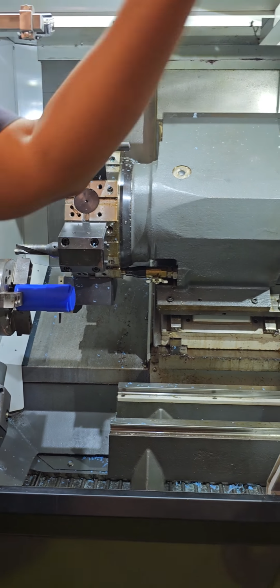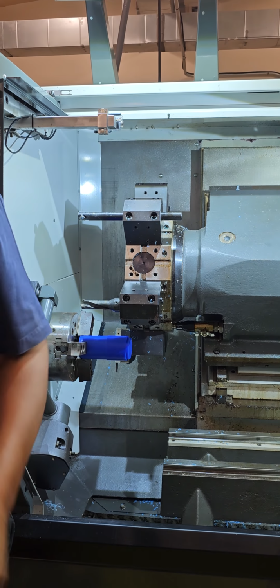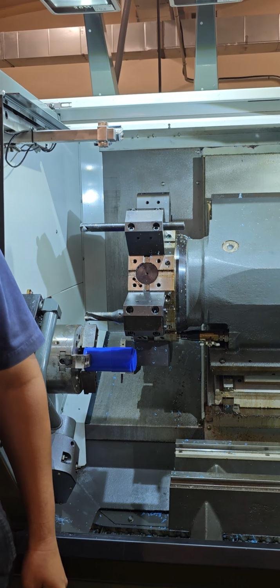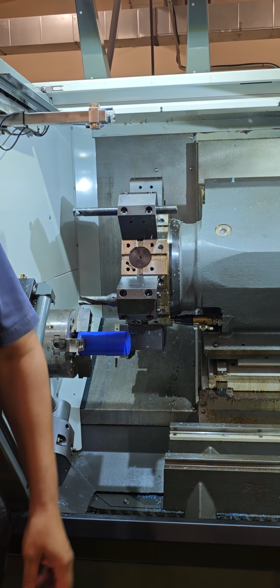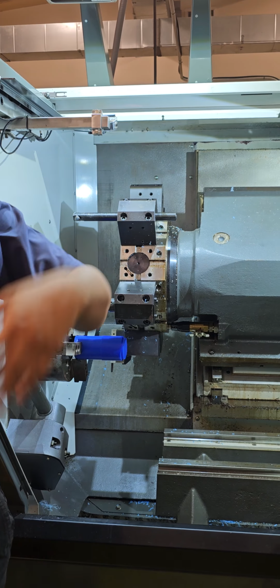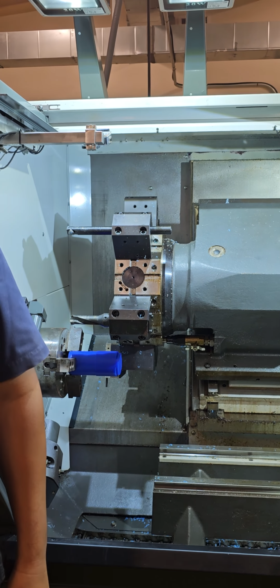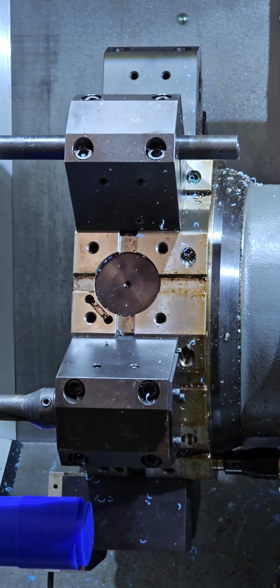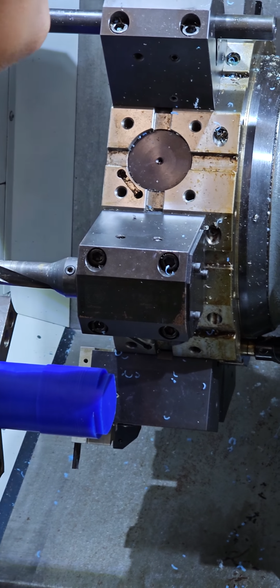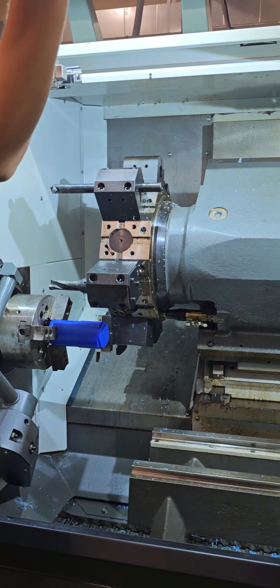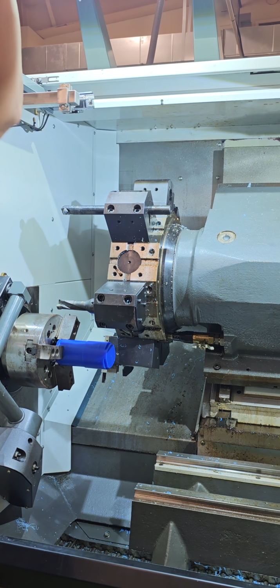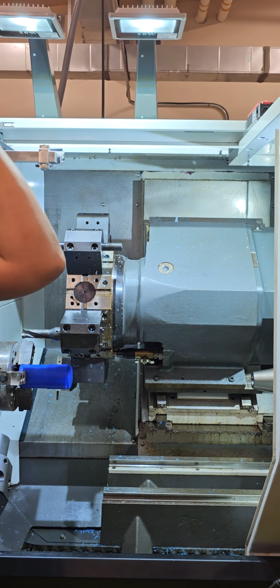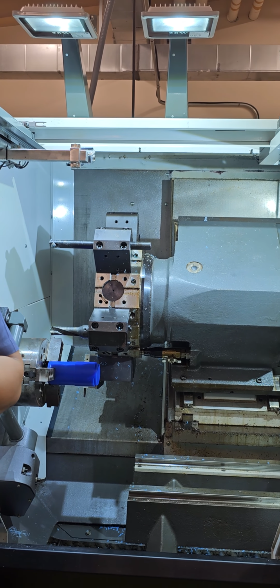Every time that you're going from OD to ID, you leave one empty pocket. Oh, tool pocket, right? Yeah. Now, if you have a bigger machine, probably it's gonna be two pockets. Well, the machine that we used to have over here, two pockets. So right now, I have an OD tool number 1, OD tool number 2, and now I'm gonna use a drill. So that's OD to ID. So we skip 3. I have to leave at least one pocket for safety. Gotcha. Got it? Yes. All right.